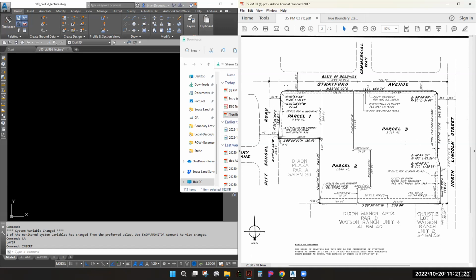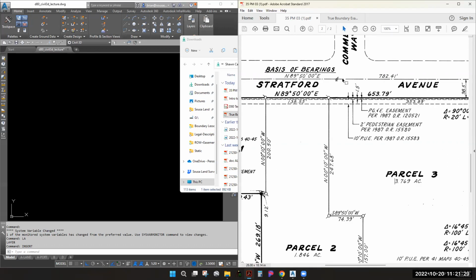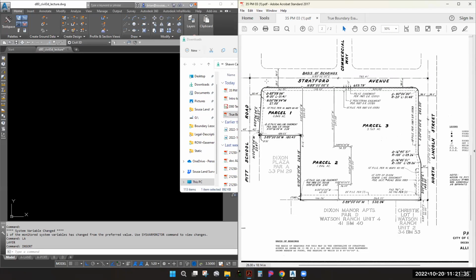If you've taken mechanical, it's exactly the same in civil, center line type. And you're going to see a CL on there, typically. CL means center line. So you're going to look for that line that surrounds the property, and then you're going to look at your boundary line. We're going to use the center line to build the property line.